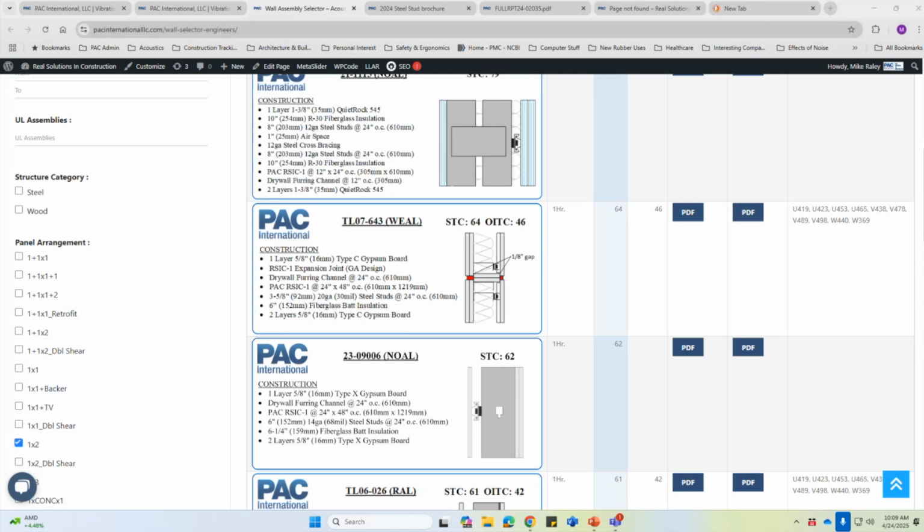Right. I have clients who say, "Well, I went to the Virocon glass website, and they said that this glazing gives me that." I say, "Yeah, but you have to put it in the frame." Okay. Yep. The next thing is when you mentioned you have to fill that small air gap when you're furring stuff out. The problem is some people have a half-inch gap, but they try and put 1 inch of fiberglass in there. And by compressing the fiberglass, you're creating another structural path.